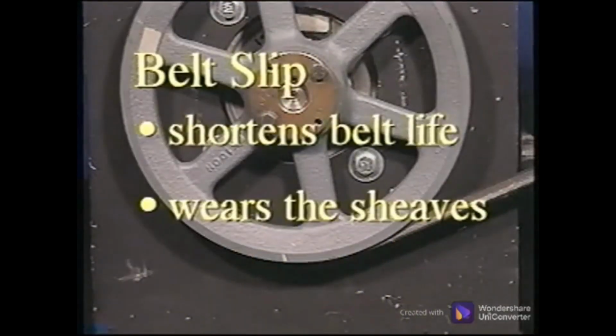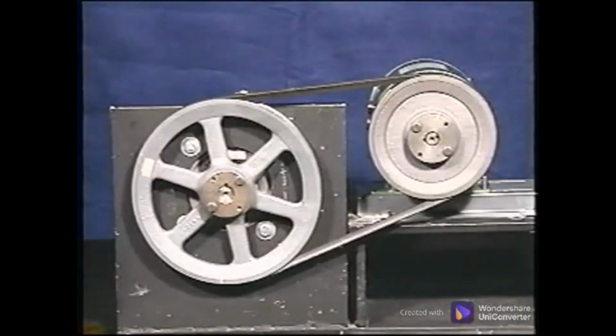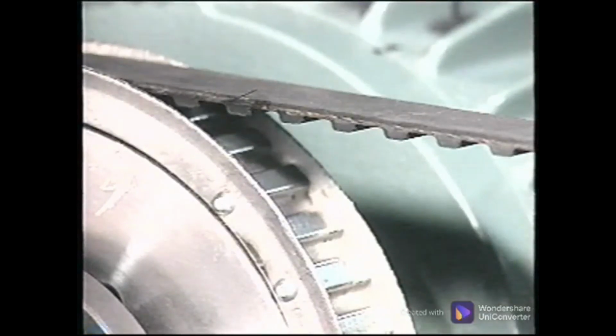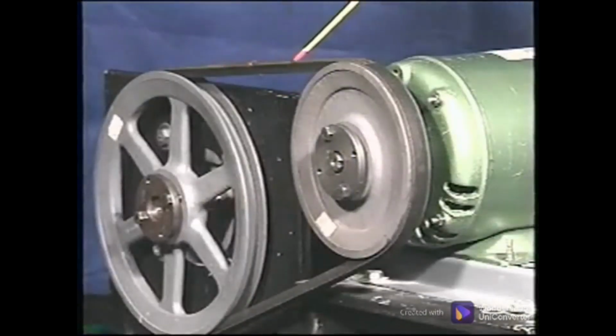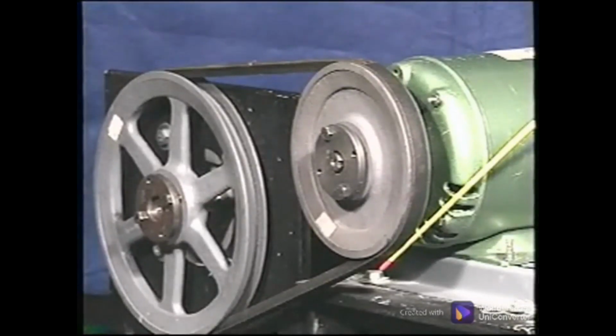Belt slip generates tremendous heat, causing slip burn on the belts, which substantially shortens belt life and wears the sheave. Belt slip occurs in all belts except the positive drive timing belts. Another condition that results from the high loading of belts is belt creep. Since the tension side of the belt is stretched, the driving sheave receives more belt than it gives out.